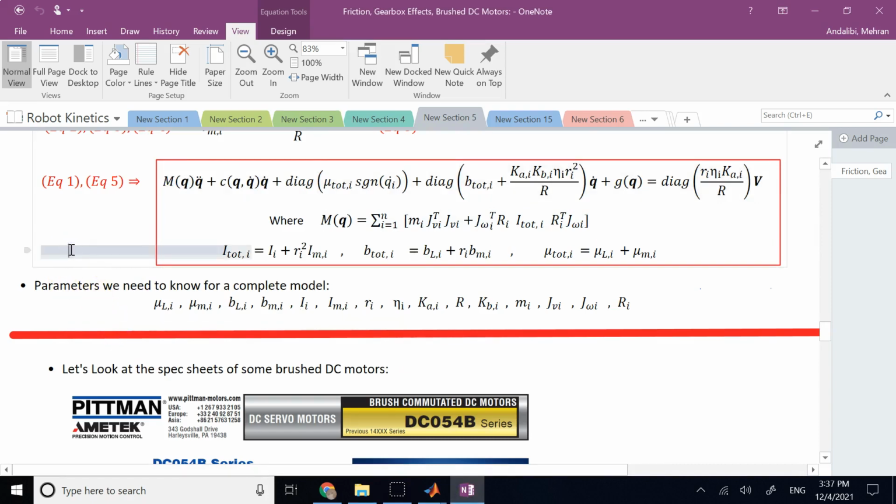And we are going to apply this to the planar 2 degree of freedom manipulator, for which in one of my previous videos I have found for you the J_vs and J_omegas, the portions of the Jacobian for velocity, linear and angular, the rotation matrices for each link, the inertia matrix for the links, and the gravity terms, the Coriolis and centripetal terms, right?